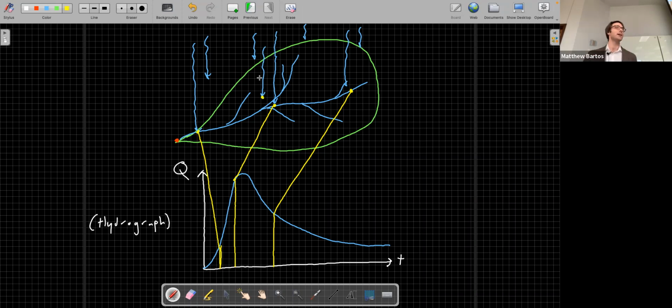One is that it might end up as overland flow. So this will land somewhere near the middle of the watershed, but it has to travel slowly over the land surface before it gets to the channel, where then essentially it takes this highway down to the end of the watershed. So even though it lands near the same location as the one that landed in the channel, this will appear somewhere a bit further back in the hydrograph.